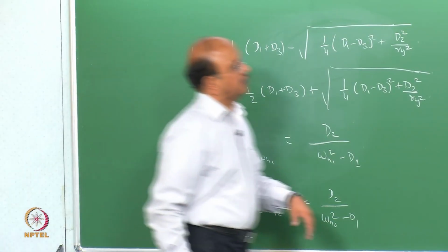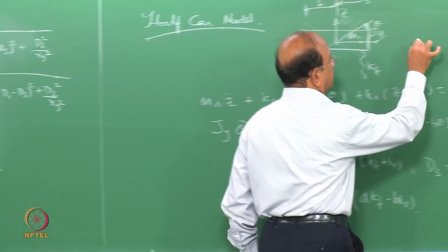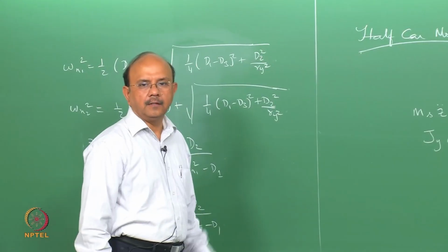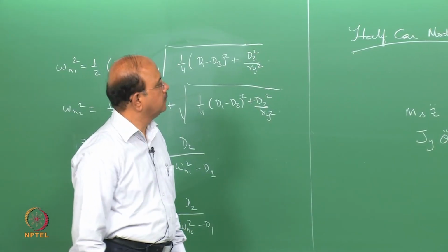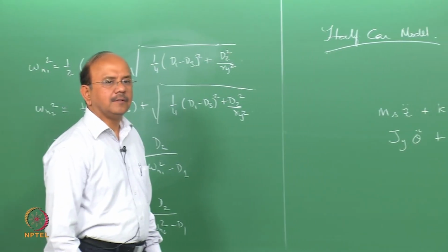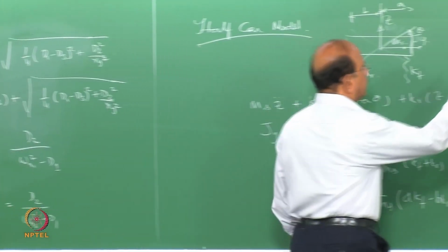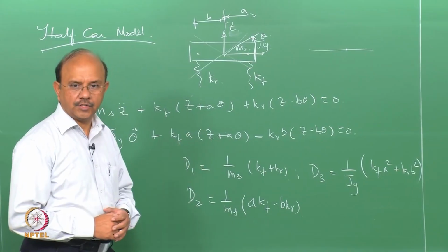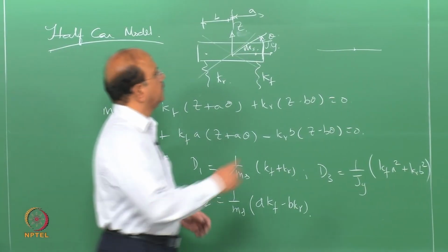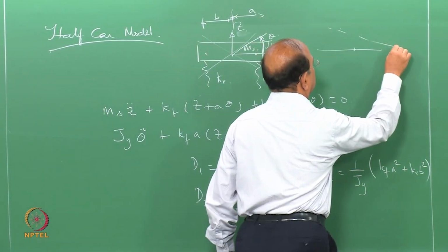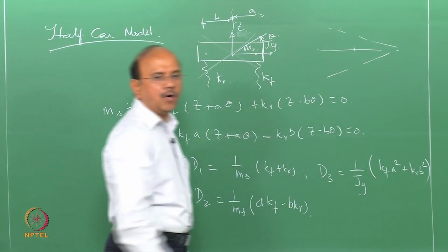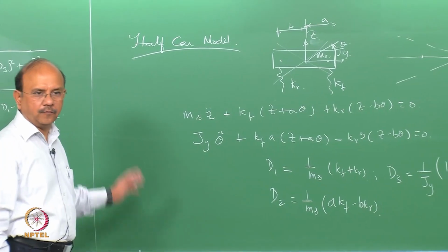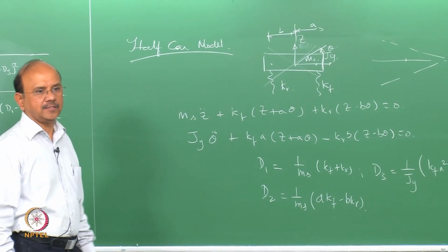In other words, if I now just represent my vehicle, the sprung mass, by a straight line, and this happens to be the center of gravity location, then the oscillations would be about a node for the first natural frequency, something like this.